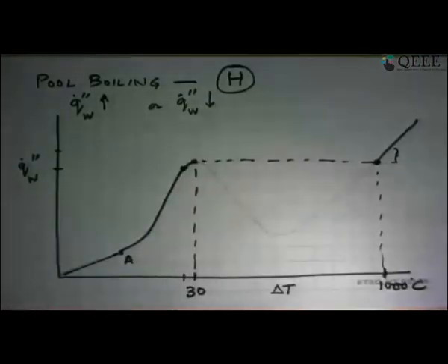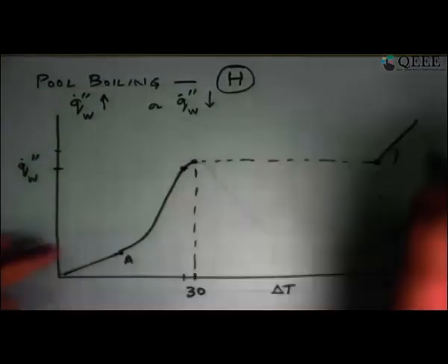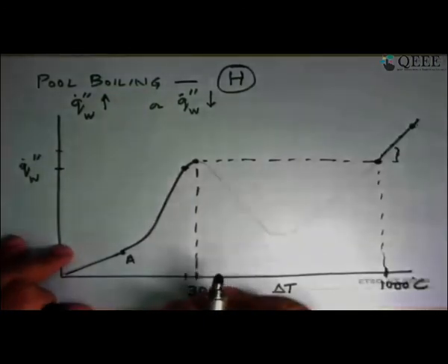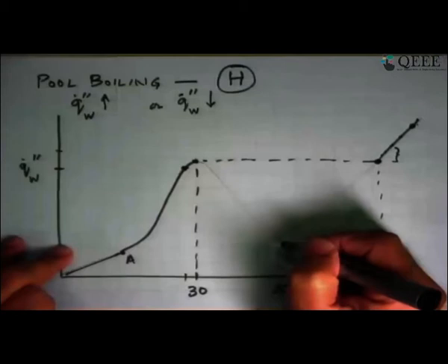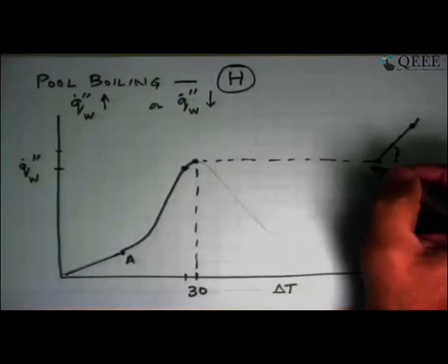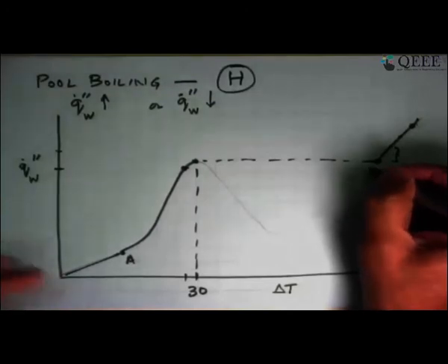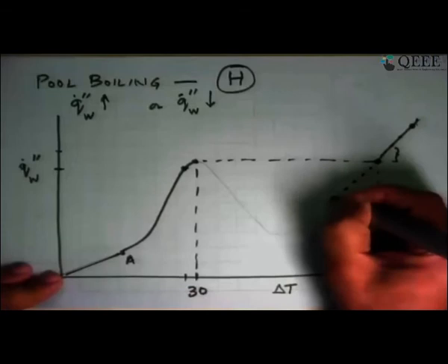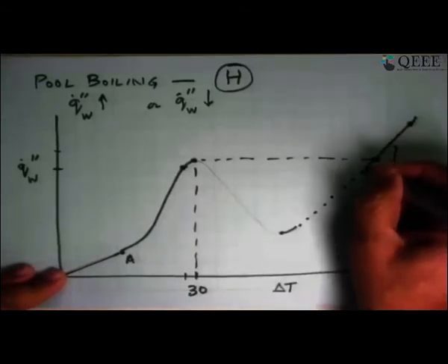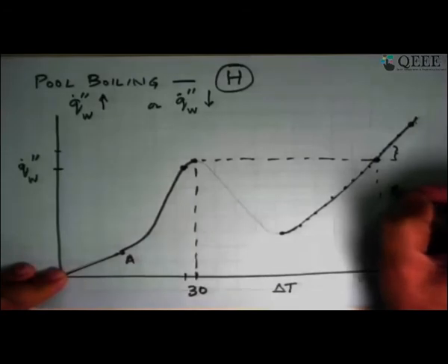So this is what happens in the constant heat flux case. And let's see what will happen if we do the reverse. Suppose the material did not fail, we started from this condition and started decreasing the wall heat flux. So we came up to this point. And then as you keep decreasing it, because the film surface is there, that film will start getting weaker and weaker, and finally it will reach the Leidenfrost point. So these are the states that it will follow on the cooling side.